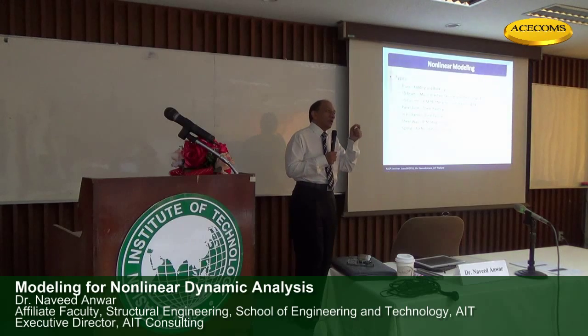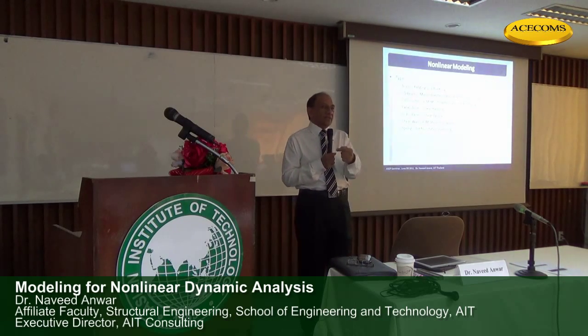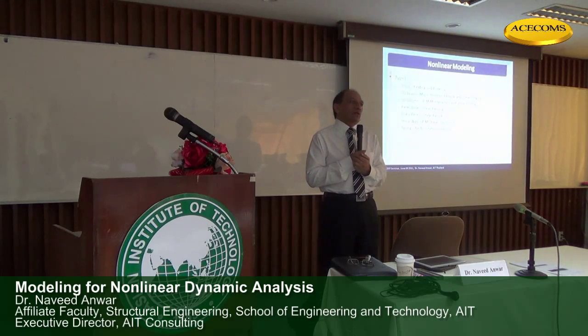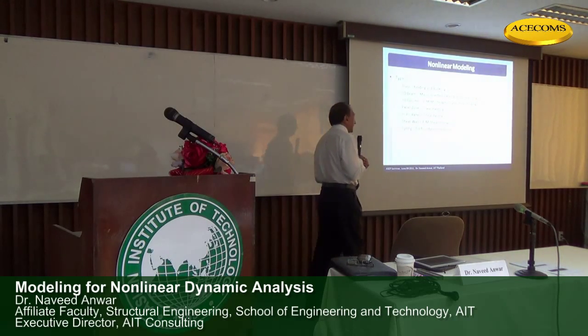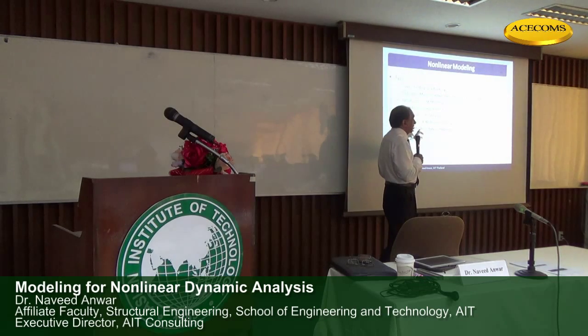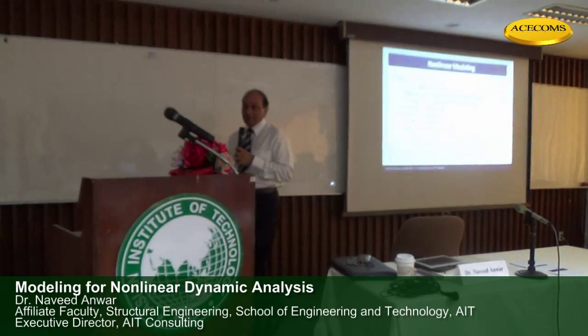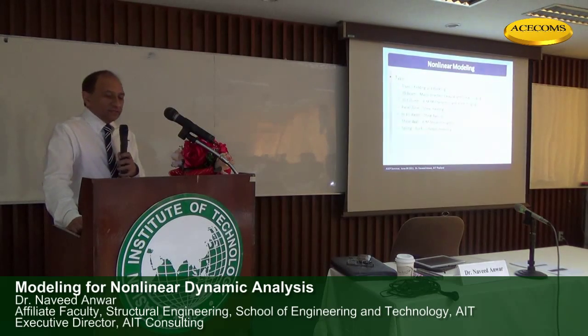That's why we normally have to consider the shear to be elastic, so we can take it out of the equation and only consider the nonlinearity of the bending. But in reality, that's not true. Springs for foundation modeling could be a nonlinear link. So this is what we can do for a typical structure which is composed of these components.